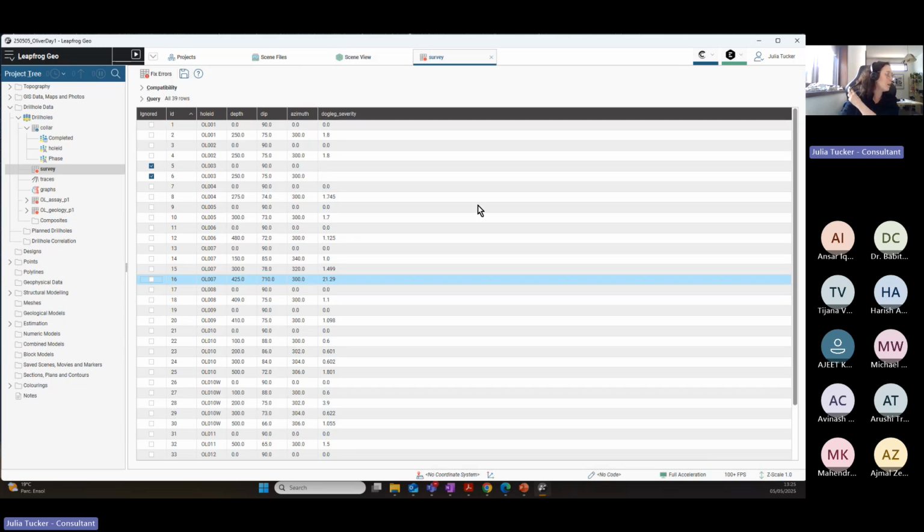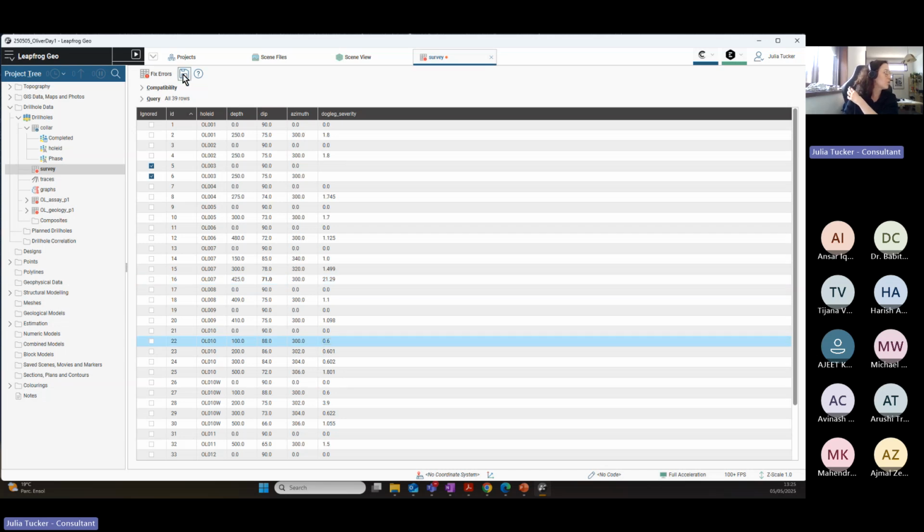So now that we have opened the survey, we can just check right here what is the problem that we have with it. And we can see that we have another typo problem. So we just need to double click on it and take out the 0. So in the OL007, we just need to, on the dip, change the angle, because we had a typo here that was 710, and we could see, visualizing, that we have an error on the survey, and now we just need to save it.